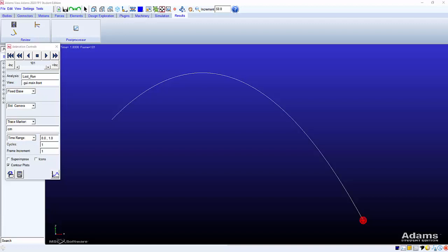When the system equations are solved, the results will be stored in the program, either intermediate file or external results file. One of the post-processing processes is to animate the model. What is animation? Actually it is the graphical representation of the model at different positions, at different frames, at different time steps.